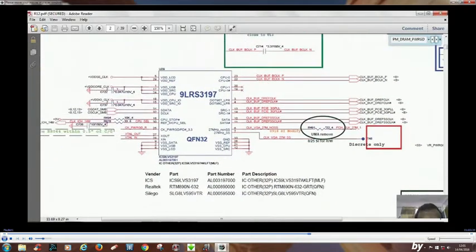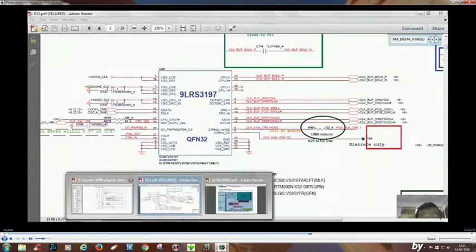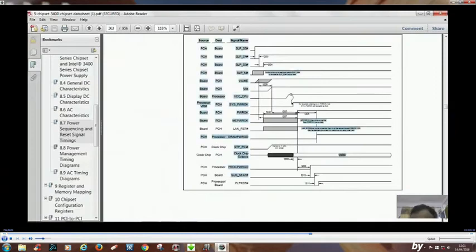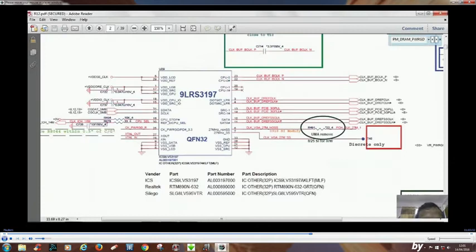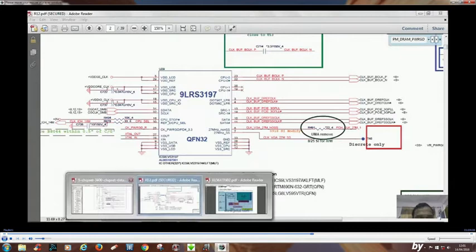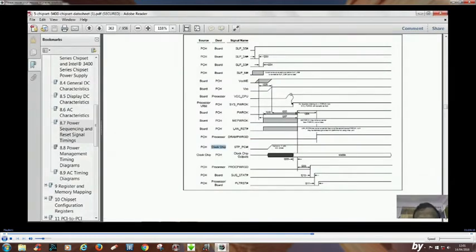In some kinds of clock generator you will find CPU_STOP is basically connected with the stop PCI, but here this is connected to the plus 3V. So this stage is not required here because the clock generator is getting turned on in this schematic diagram after the core voltage regulator provides the enable signal, right? In some kinds of schematic diagram you will find this CPU_STOP pin connected with the stop PCI, and this stop PCI is coming from the PCH.